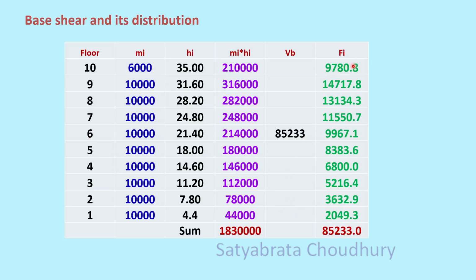So these are the forces which are your design forces at the floor levels. You can put these forces at the center of the slab in some established node. At each slab level, each floor level, these forces are to be put. Then you carry out the analysis and carry out the design. So this is the background before going to the software. You cannot do actual design without a software like SAP 2000 etc. So before design, the design forces are to be computed manually like this, maybe using an Excel sheet, or you can make a C program or some program.